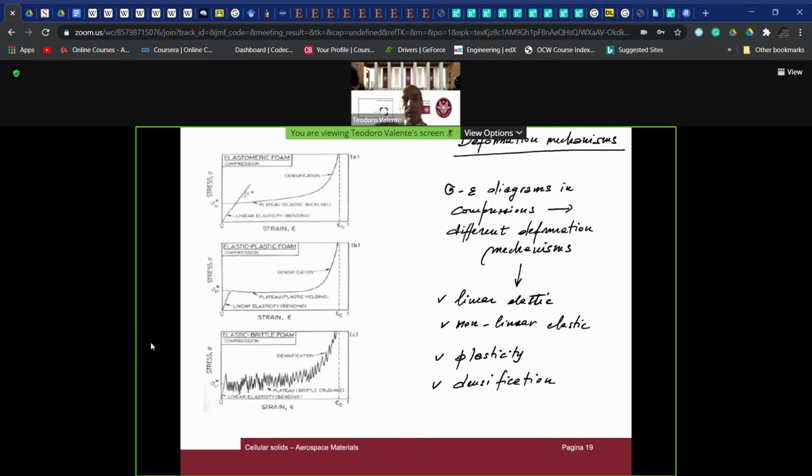And so this means that here we start, just to explain to you, for example, with the fracture of one beam, then the load is redistributed among the others, then we reach again the strength, and thus the rupture of another beam of the single cells, and we have this fragmented response in the case where the base material is characterized by an elastic, brittle behavior.